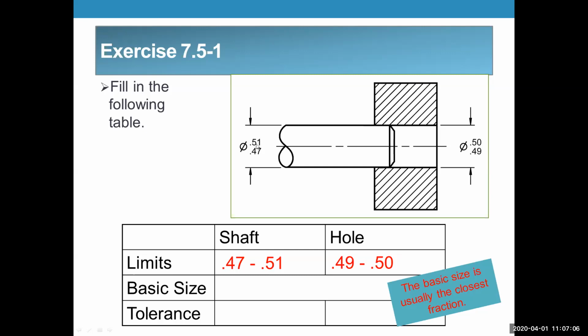And I know from experience there's more than one time that a machinist has seen that number and said, oh, that's the number I got to shoot for. And he does it for a hole, and he's got a little burr or something on his mill, his tool, and he oversizes the hole. And then the hole is junk.